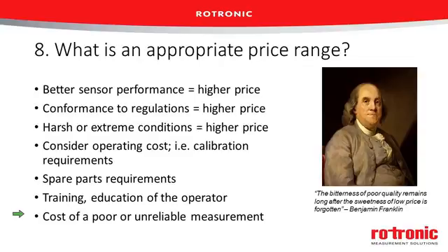Another one that I remember dealing with was a museum. And the museum had a storage room where they put some priceless art when it wasn't being displayed. And they had very sophisticated humidity control in the room. And they had a transmitter on the wall. They chose a very inexpensive transmitter to control the humidifier. And so what happened is there was an electrical storm, and because it wasn't a robust instrument, it shorted out the instrument, and it failed to 0%.